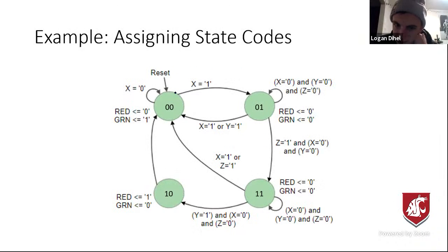So here's an example that I did. You see that if we go from here to here, exactly one of these flip-flops is changing. When we go here to here, again, we have one flip-flop changing. If we go here, again one flip-flop changing. If we go here, one flip-flop changing. I couldn't avoid it here. That one I couldn't avoid. We have both of them changing. So you just have to live with that and ask yourself, is that okay? In 214, you don't really have to answer that question of when it is okay to do that.